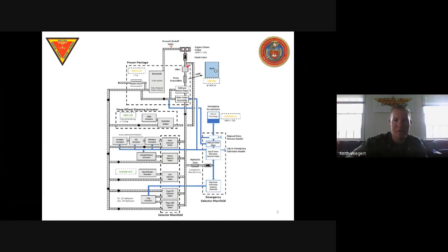Going through that one-way check valve, then we go through a filter. Filters filter until they don't, they bypass. So this is going to be filtering our oil until it gets clogged, and then it's still going to bypass, because dirty fluid is better than no fluid.